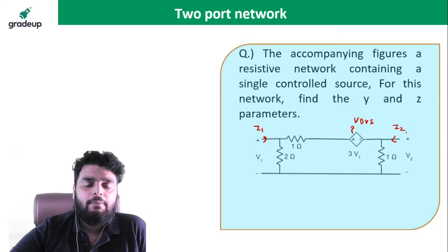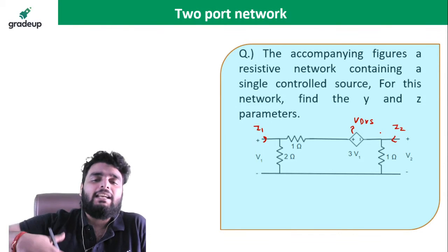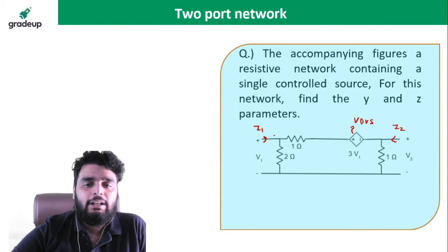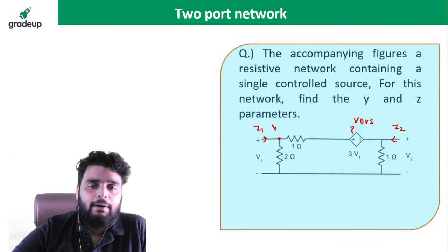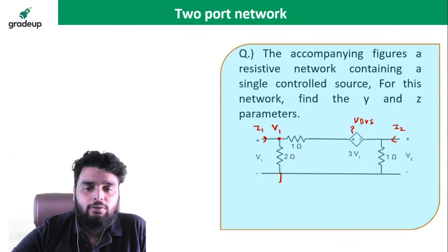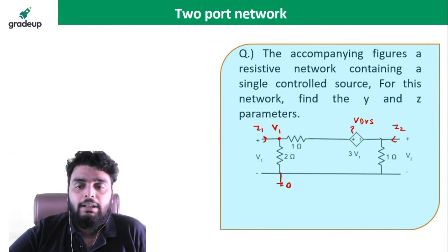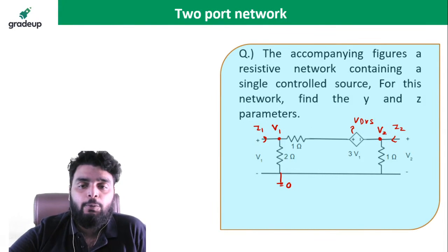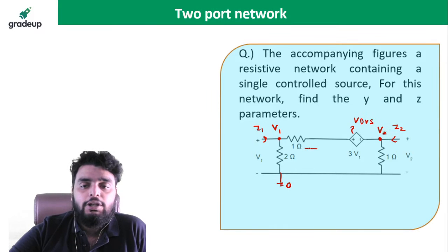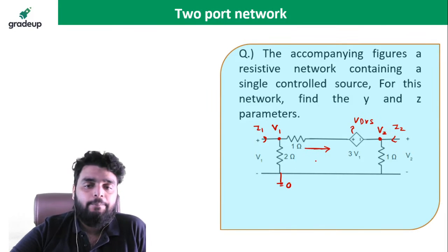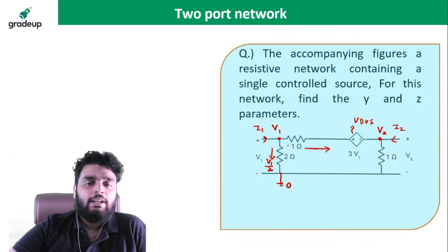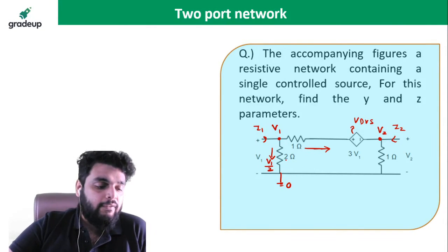Now simple है, just you need to write the KCL and KVL equation, और कुछ नहीं। तो आप देखो यहाँ पर वोल्टेज कितना होगा V1, अगर मैं इसको 0 ग्राउंड से कनेक्ट कर दूं तो कितना होगा V1। Similarly here the voltage will be V2. Now tell me the equation of current which will flow here. Here the equation will be V1 by 2, no problem. Voltage divided by resistance, V1 by 2.